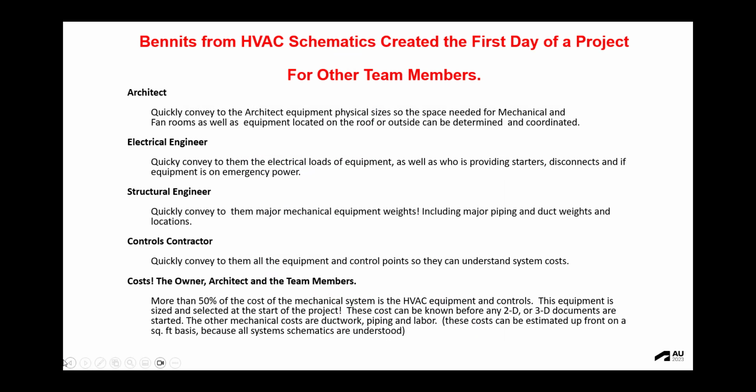So benefits. What benefits do I have by creating schematics? And I'm talking the first day of a project for all team members. You can quickly convey the architect physical sizes of space needed in mechanical and fan rooms, as well as equipment located outside or on the roof. You quickly can convey the electrical loads to the electrical engineer, who's going to provide starters, disconnects, is anything on emergency power. You know equipment weights and loads, so they can be given to the structural engineer.